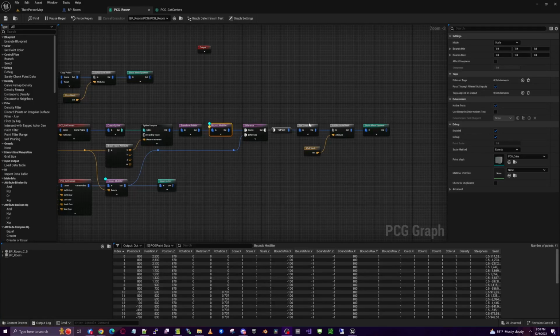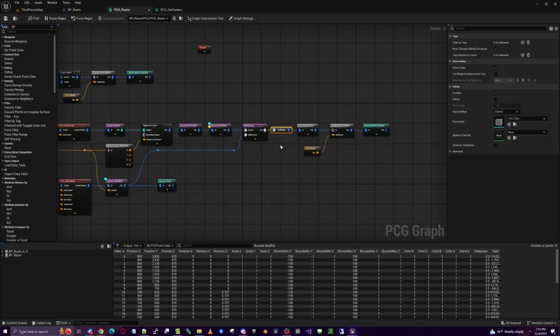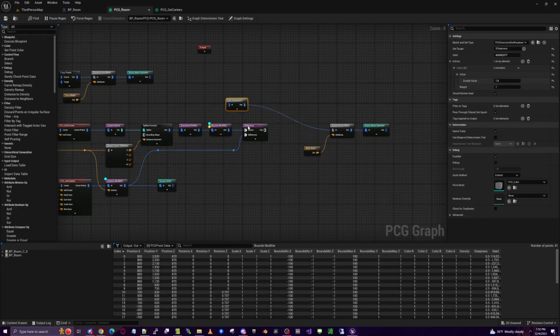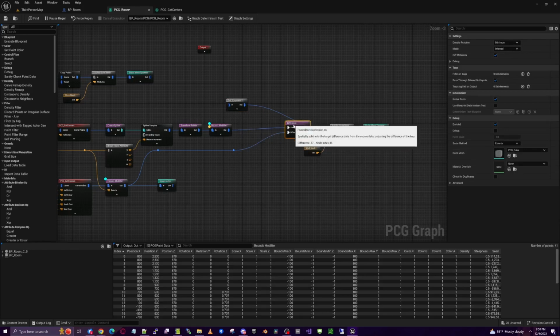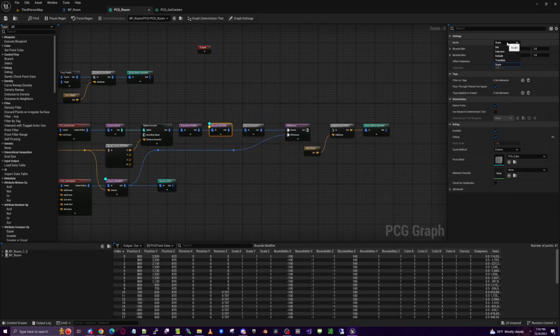So this difference should actually be after we set the steepness. That'll help out. So let's move this. The steepness setting to 1, we want before the difference. That's why we were doing that. And then we want this bounds to be a set, and we want to set -100, -100, -20, and then 100, 120. So we can see that hopefully.